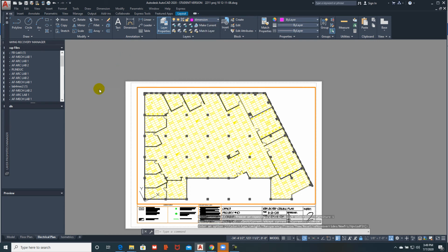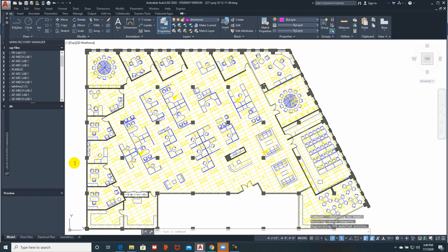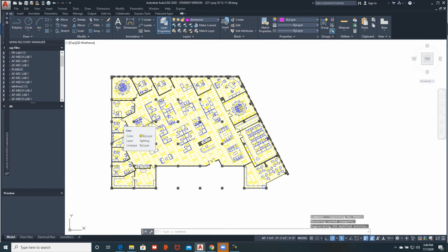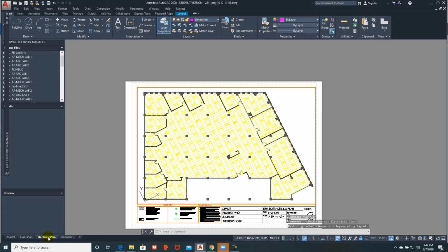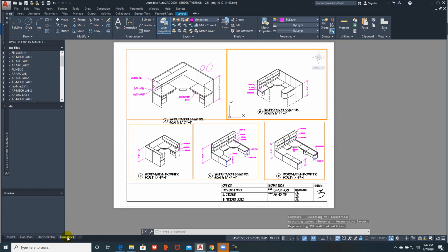What we can do is we can create these books essentially from a model of the floor plan with all these different elements like heating, ventilation, and air conditioning, electrical, data cabling, and we can put everything into a model or model space where we can get an idea of where everything is in relation to everything else. And then on the layout tabs we toggle off the viewport layering for certain elements. And so it's a really good way to be able to manage drawings.